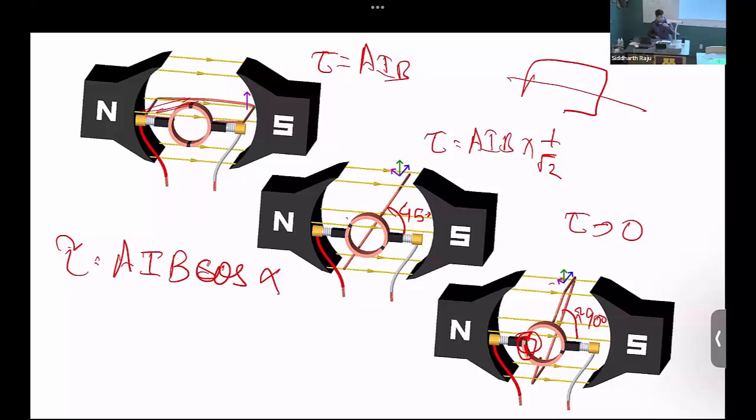So when I take a coil and put it on an iron core, what have I created? A solenoid, an inductor. Previously, when the contact was established to the outside world, there was current through the solenoid. Now, suddenly, when the contact is broken, I'm breaking a current in the solenoid. What is going to happen if I try to break a current in a solenoid? Yep, you'll get inductive kickback. So you'll get L dI by dt, which is what we saw, the arcing when we try to open a switch gear in a power system.